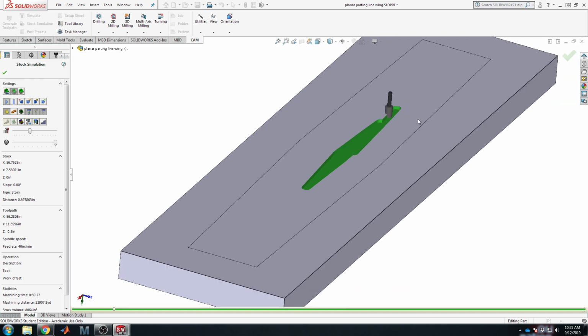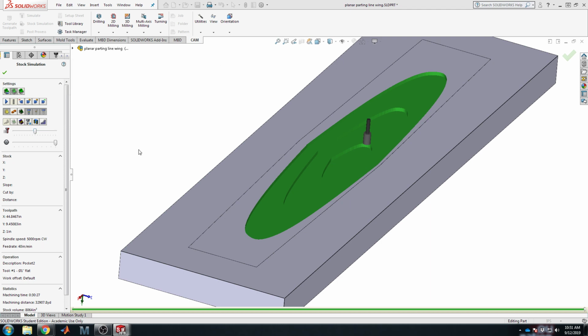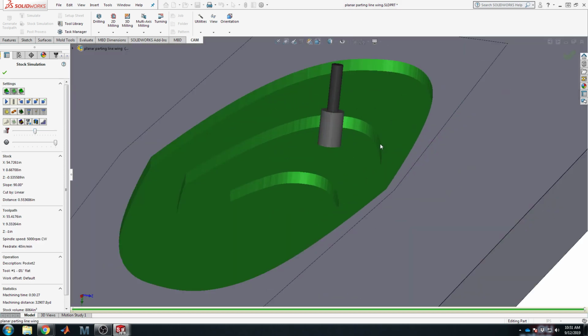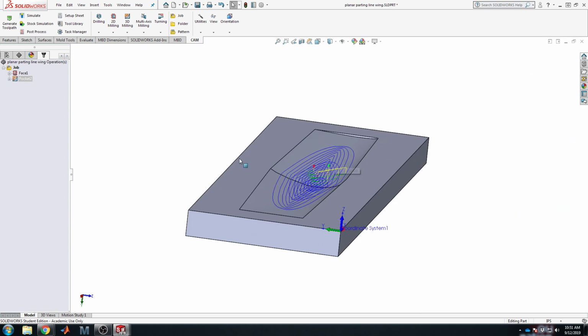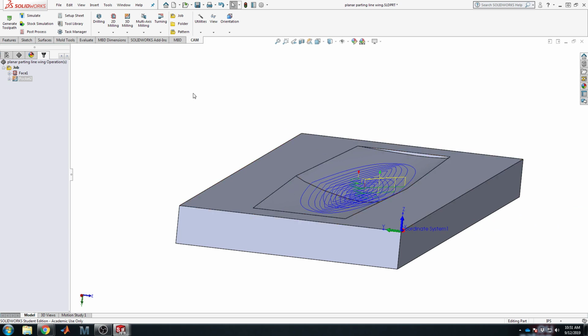And this is what a roughing pass should really look like, that it's removing material with half the cutter-ish per operation. Let's speed it up a little bit. One more notch. It's still kind of slow. And then it goes way too fast. Yeah, welcome to the party. But you see it does that for the top layer, then it cuts out this pancake shape in the bottom layer, and middle layer, then the bottom layer, and you're good to go. So that is roughing, which is nice. And this is basically just to remove material so that whenever you put on the more fragile finishing bits, it's able to cut the final surface without loading up the cutter head as much.